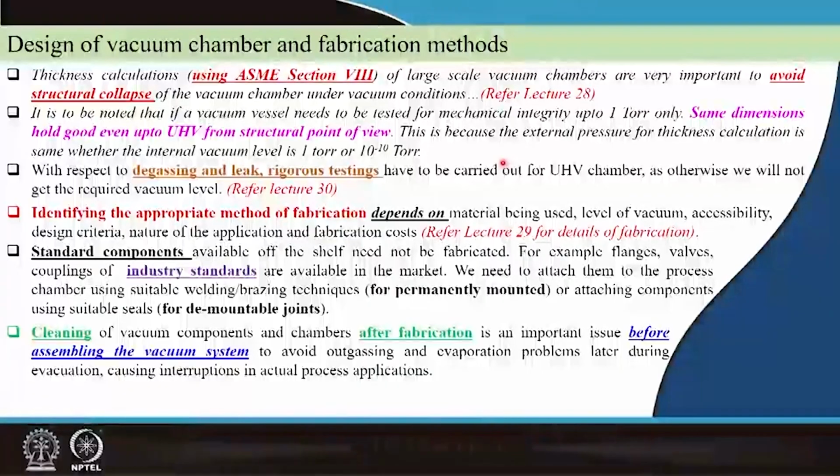Okay. Then from the ultra high vacuum point of view, leaks, degassing issues, you should know the physics of degassing, the chemistry of the degassing, what it is degassing. If it is degassing helium, how does it matter? If it is degassing argon, you do not care, let it degas, it is not going to interfere, it is not going to make compounds, because helium, argon, they are inert gases, they are so inert, they will only be watching like your stainless steel chamber or any other manipulators.